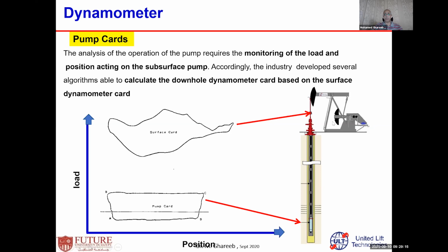And one of the engineers, called Sam Gibbs, started to analyze it and said, okay, let me simulate the performance of the rod string like wave equations, like wave behaviors, and simulate as if he moved this load cell to the top of the pump and eliminated with these wave equations, with a lot of factors, the rod weight, the friction, the pumping unit, and only has the weight of the fluid over the pump, which can be measured here for the downhole.